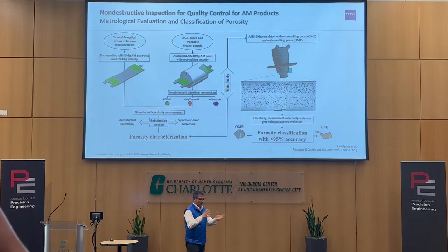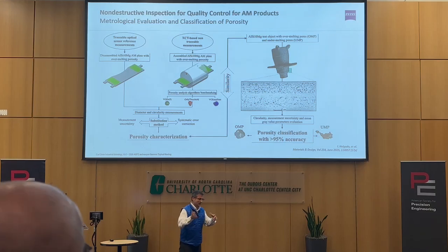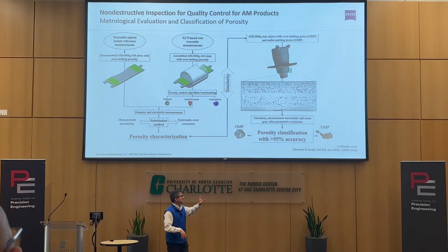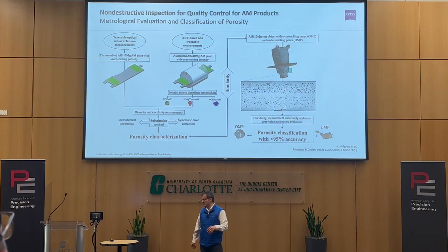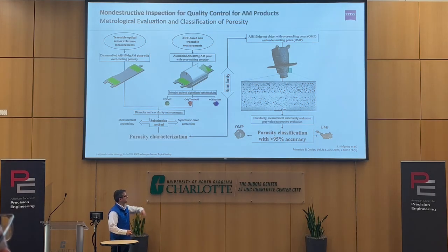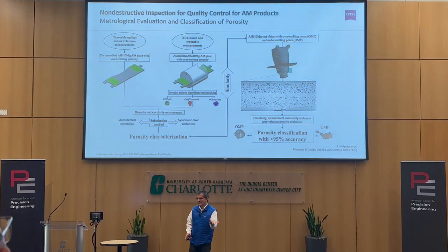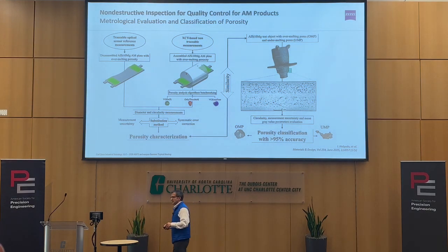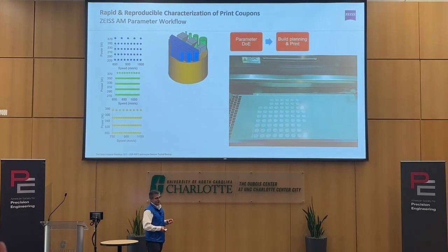We have known for ages how we can do porosity evaluation with CT, but the question still remains, how accurate are those computations when people are telling you your part has this much porosity, or this pore has a given volume and dimension. Have they done the right sort of calibrations to make sure that those dimensions are accurate? So we borrow techniques or concepts from the dimensional metrology world to try to do assessments in those calibrations. Again, you can just read the papers that have been published.